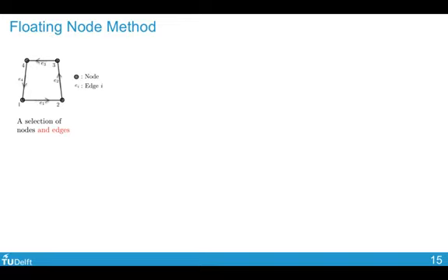But now with fracture, most of the time, a crack would propagate across the edges. It would cut across some of these edges, and then you are introducing additional crack nodes on these edges, and numerically you are introducing additional degree of freedoms there. So at this moment, your previous fundamental assumption that the element behaves continuously throughout the analysis is no longer valid.